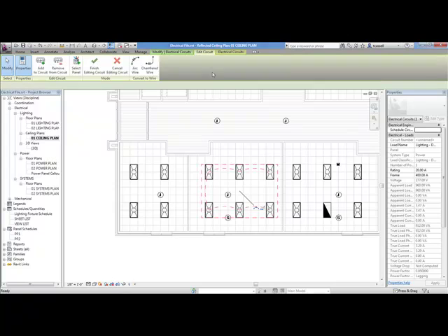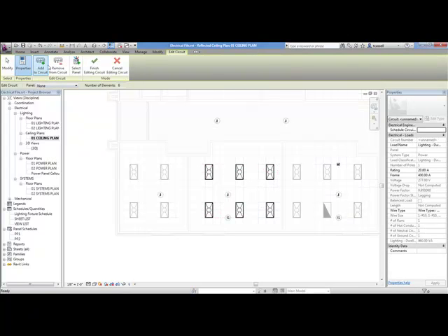When I create that circuit, you get the ability to say, yep, all of these lights are on the same circuit with this junction. Oh, that's not for these lights, but with LP1. What happens is these lights now go on LP1 automatically, and it only shows you panels here that are available for 277 volt circuiting. In other words, it's not going to give you any of your power panels because all your power panels are meant for 120 volt for this.